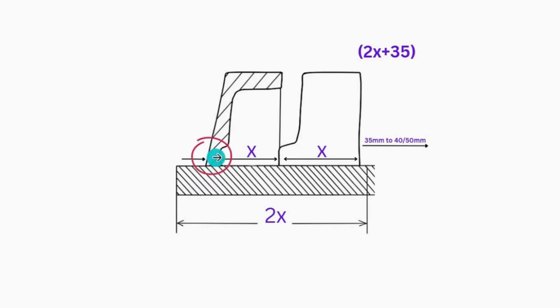So, can you tell me what this thickness is? If I tell you this is 2.5 mm thick, can you tell me the coring thickness? Usually we try to maintain the same thickness in the doghouse, and in the coring out area it will be maybe 1.5. Why 1.5?